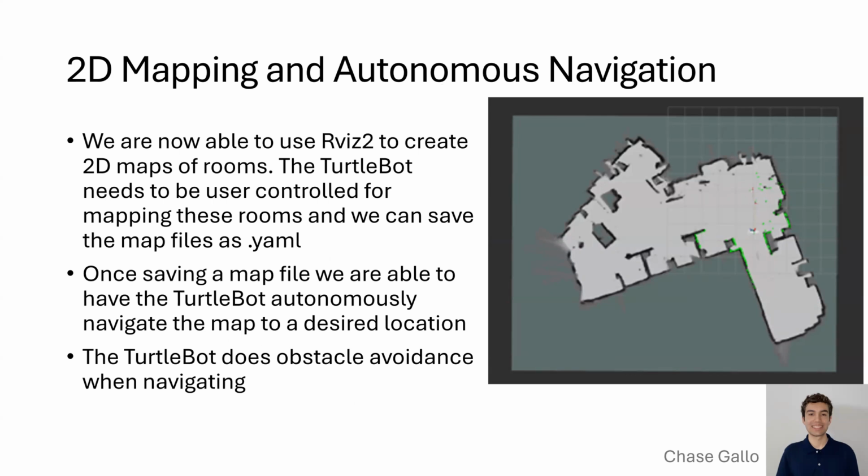So next, we were also able to do 2D mapping, which uses a technique called SLAM, which stands for simultaneous localization and mapping. And we basically draw a map by estimating the location of the robot in a space, and then once the SLAM is up, we will move the Turtlebot around, as Jesse was describing earlier, with either a Bluetooth controller or teleop commands from a keyboard on a laptop. And we move it around, and the Turtlebot running the SLAM begins to build the map. And we went through the DaVinci lab in the Engineering East building and mapped it as shown on the right. The white area is open space, and then the black are walls, and the robot obviously cannot run into the walls, so that's how it represents it.